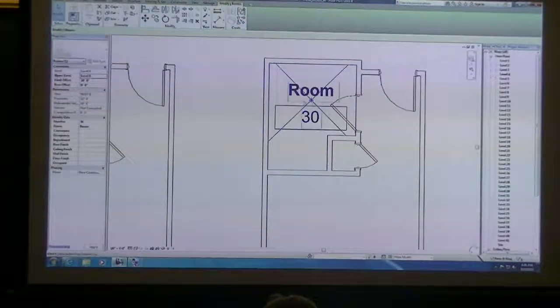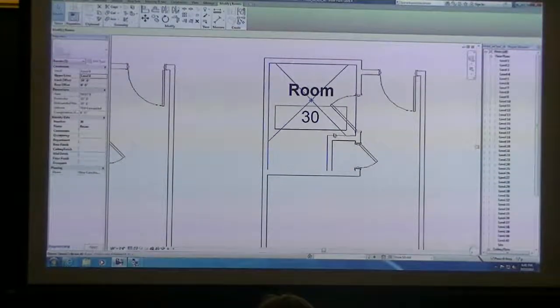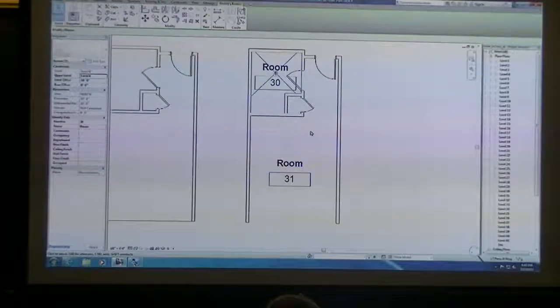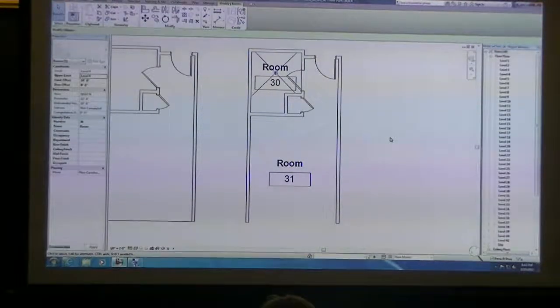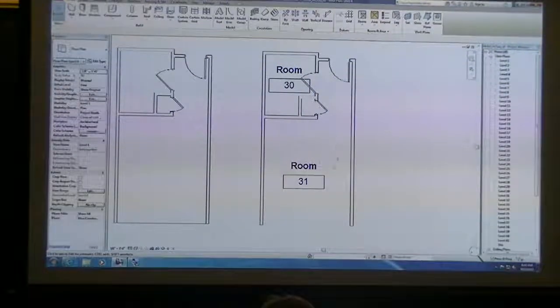By placing rooms and spaces, this is how Revit can manage and extract the data from whatever architecture and spaces you're creating. Later on, just like we did a mass floor area schedule, we could do a room schedule and schedule out exactly the square footage of this particular space. Or you could click on all these and add them up.